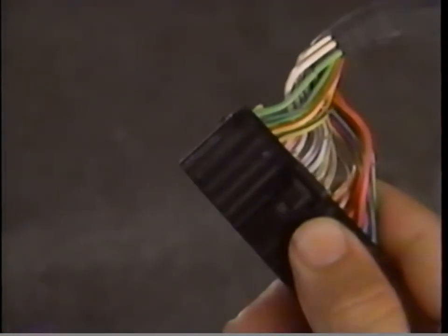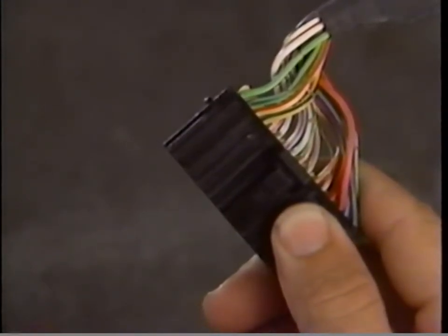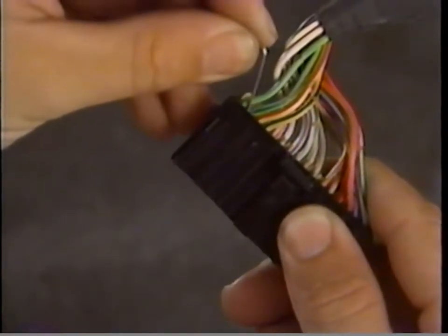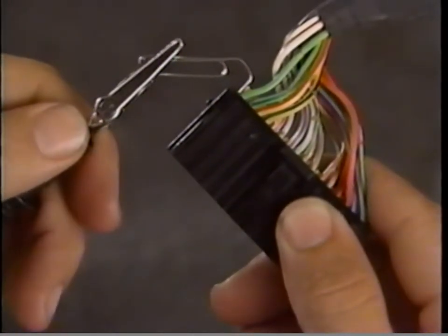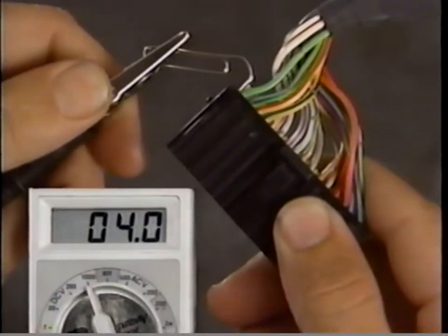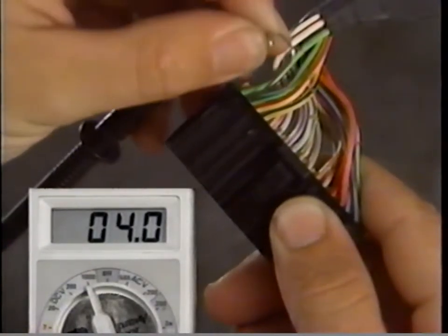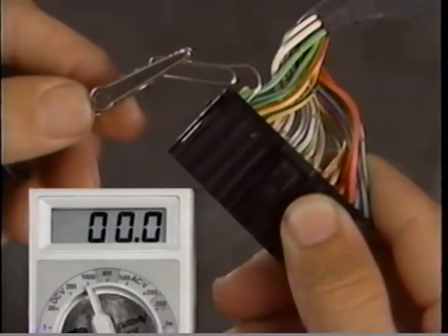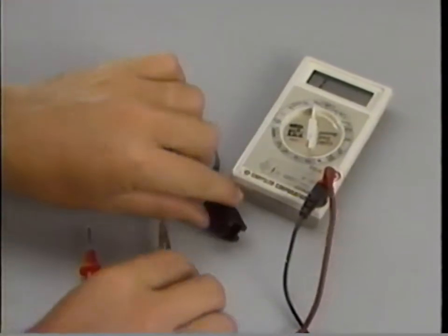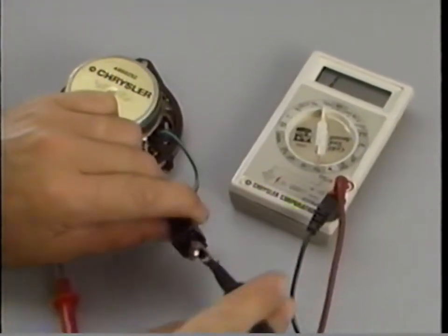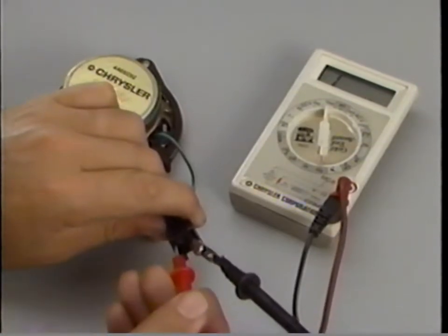After removing the rear trim panel in the trunk and disconnecting the amplifier connector, check for a short to ground on both leads going to the speaker. You should always get an open circuit reading when doing this test. Here we have a reading of 4 ohms on one lead and 0 on the other. Since we do not have an open circuit reading, we have narrowed the problem to the harness. If our problem was not the harness, our next step would have been to test the speaker. Here, we should receive a reading of 3 to 5 ohms.